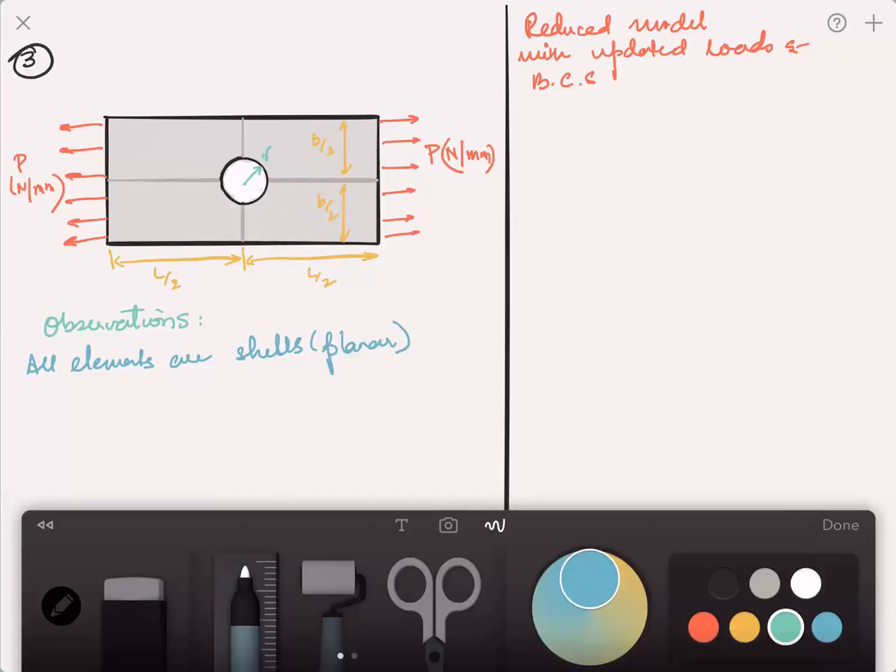The load that's applied on the two sides is exactly the same. So what you don't see here are the boundary conditions. This is a very classic problem, and there are certain ways to deal with it. What you basically want to see is a behavior such that once you start applying the load P Newton per millimeter, which is a distributed load on both the edges, your plate will start basically expanding in both directions, and you will see a certain final shape under this load, a bit exaggerated here, which looks somewhat like this.